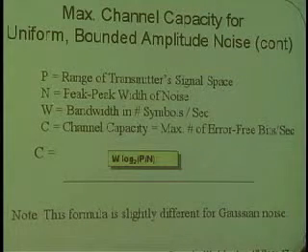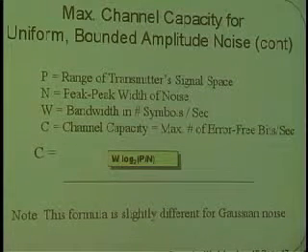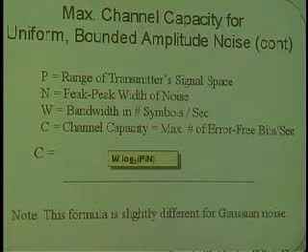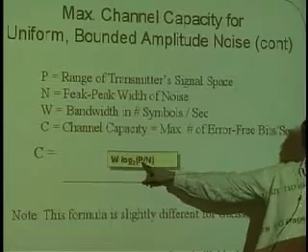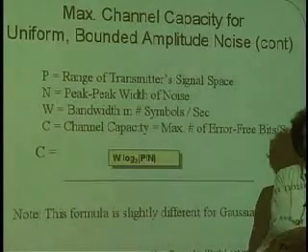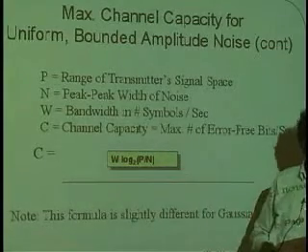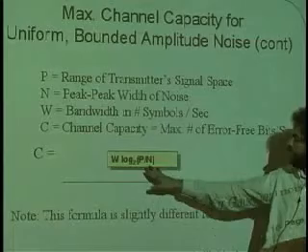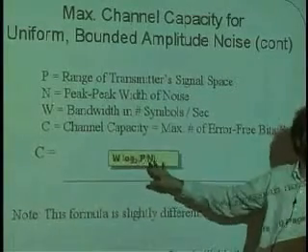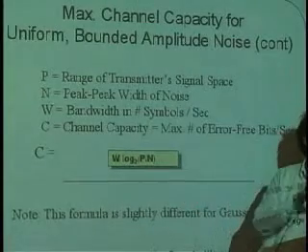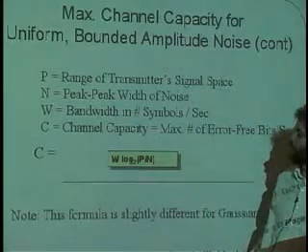This formula that's right here is the formula for channel capacity that Claude Shannon figured out. What he figured out was that in general, if a transmitter has a power P, which is equivalent to how large of a space it has to pick from in sending a transmitted signal, this is the length of the bar, and the noise in the channel is N, then log base 2 of P over N is a measure of how many bits you can send per symbol in the channel.